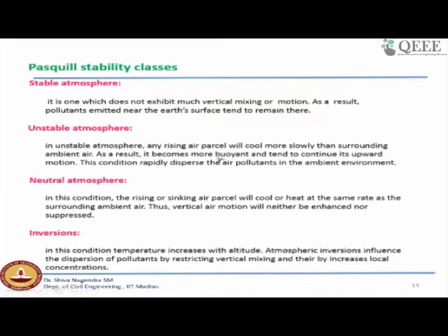An unstable atmosphere, as I told you, is very good. The air parcel released from any stack will try to lose its temperature adiabatically, so hence there is a better dispersion. In a neutral stability atmosphere, a rising air parcel will try to move upwards equivalent to the dry adiabatic lapse rate.